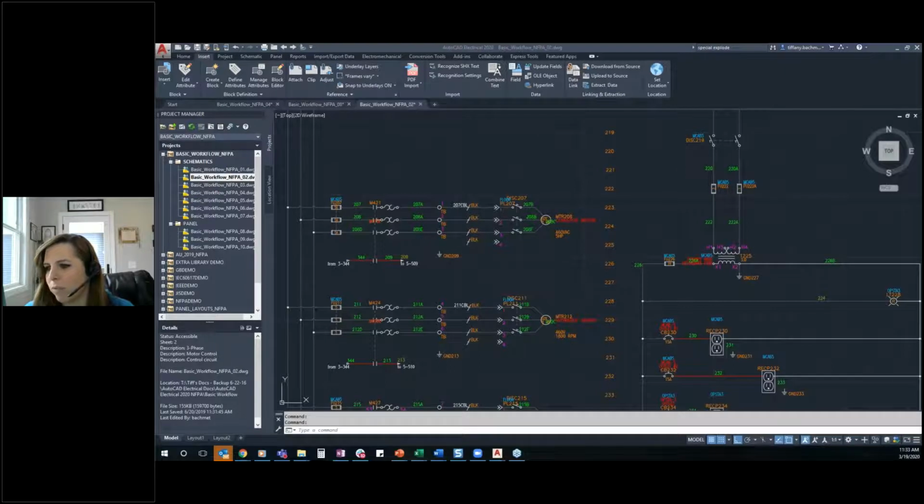We use electrical with Vault. Where should we put our catalog database? So this is a great question. It's one we address often in this webinar, and obviously it's top of mind for many people. The most basic implementation of AutoCAD Electrical and Vault is purely just connecting the drawings and the project files within Vault and managing those that way. That's the most simplistic implementation of it.